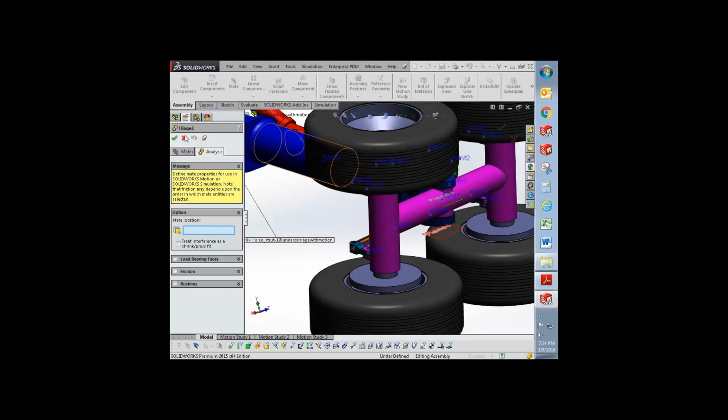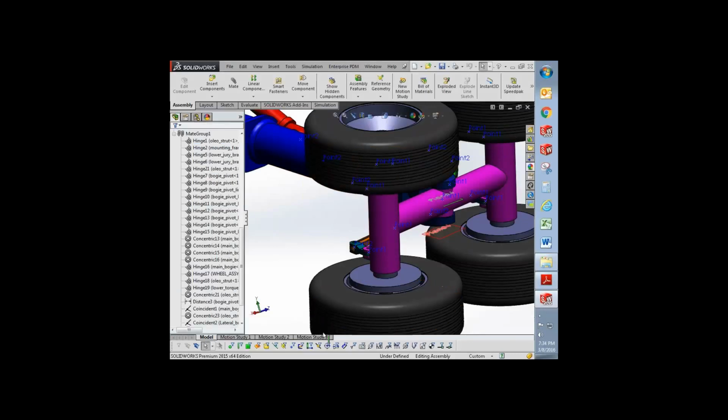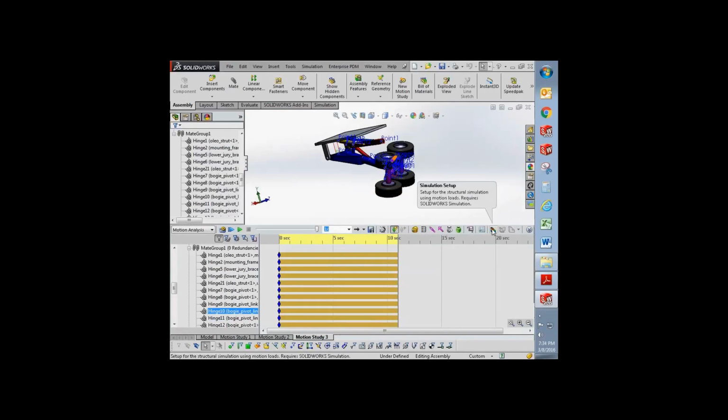One of the things you can do, and I don't have time to do it, is a stress analysis by transferring the forces from those parts to that actual part and doing a simulation right here in motion. It'll freeze at that step, get the forces, transfer them, do an FE analysis and give you the results. It's not a flexible body where the part is deflecting as it moves, but it can freeze it at that frame and say these are the stresses on that part. So the points also help make sure the simulation is at the right place.